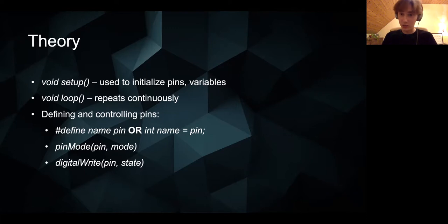But just to remind you of some programming basics: all Arduino code can be divided into 2 parts. There is the void setup part. In this part, you set up all variables, all sensors, all motors, and that kind of stuff. And one thing which is important to remember is that it only runs once.